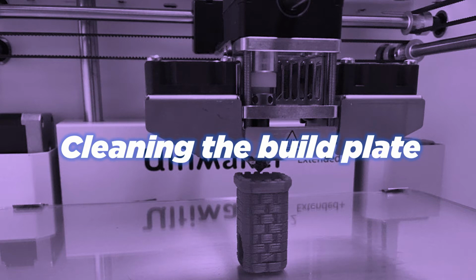Or the results from the broken tool head to the part slipping off the plate will be on you. Because I have selected silver PLA, and because the borosilicate heated glass plate for this machine is already suited for printing PLA with no extra films, coatings or glue required, I just need to confirm that the plate is clear of parts, cleaned of residue from past print jobs and free of the natural oils from fingers touching the glass surface.